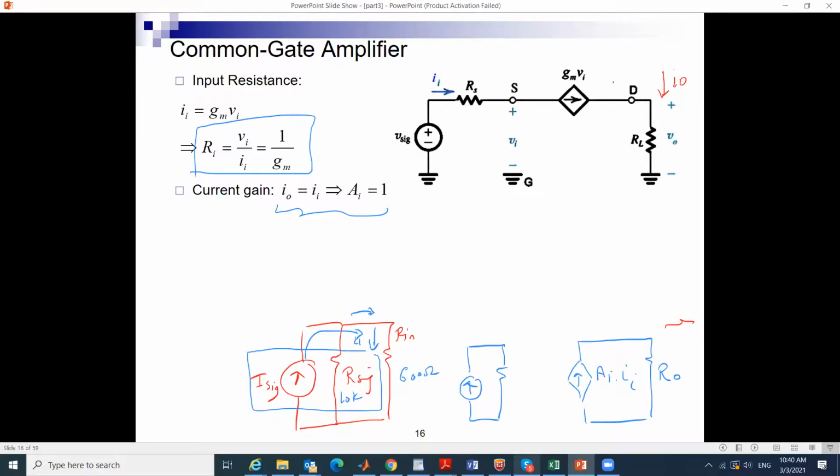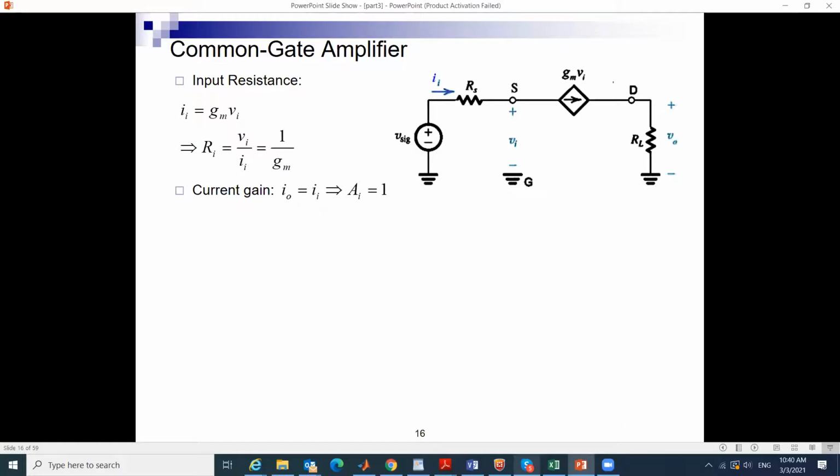To absorb most of the signal from the input signal that I have on Rn, and then I feed it to another amplifier which is going to amplify it. So these are the little tricks that can be used. Now for you, what you need to know from this circuit is that it has a small Rn, it has a current gain which is equal to 1.